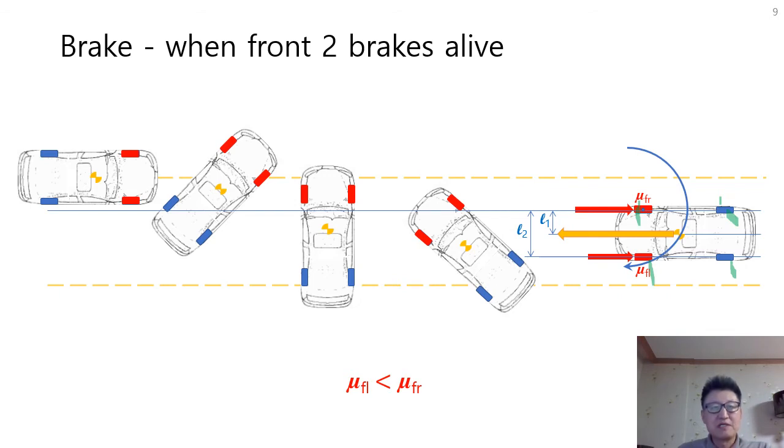Assuming that the right-hand friction coefficient is larger than that of the other side, a car tends to rotate clockwise. As you see, we have the CG location here. At the braking, car weight produces the moment with moment arm length L1 here. This moment turns the car about the vertical pivot axis passing through the center of the front right tire contact patch, because CG is on the car longitudinal center line here, parallelly placed the distance L1 apart from the longitudinal tire center line here.